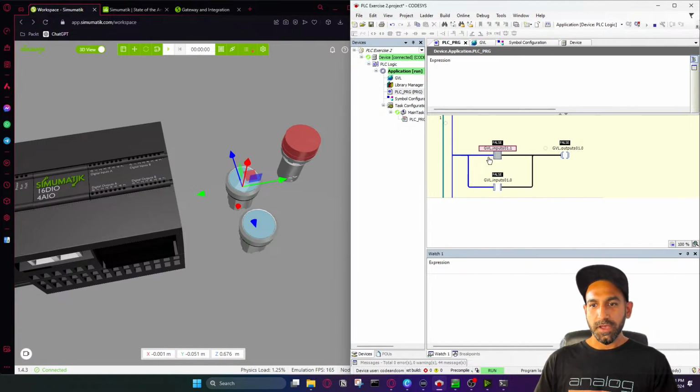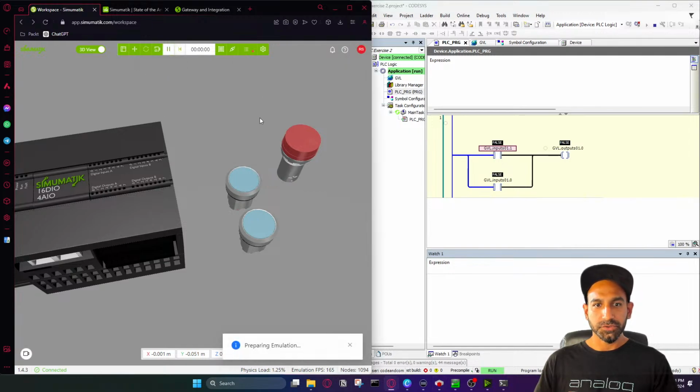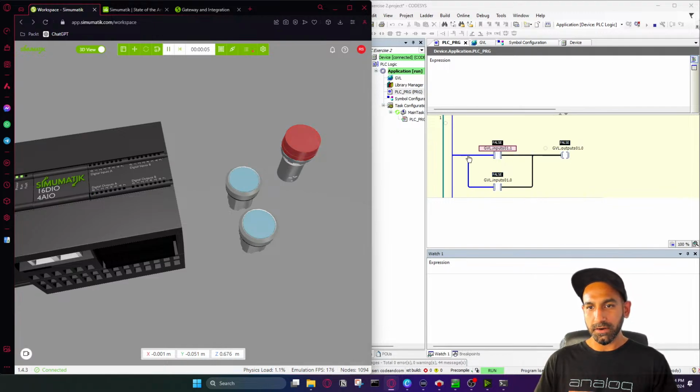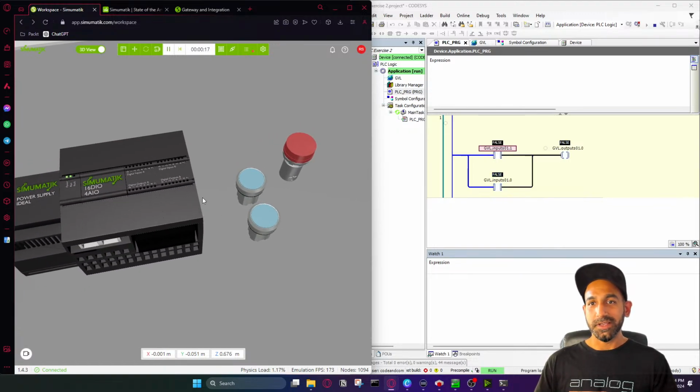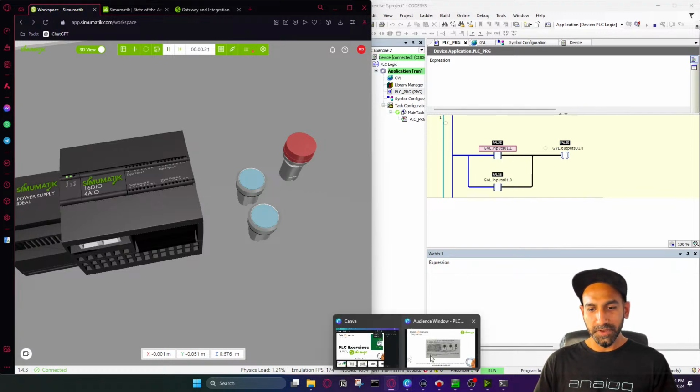So right now you have two inputs. So if you press any of the inputs, the output should be true. So in this case, you can see that output is true, and this is actuating the parallel ladder. Okay, and this one is actuating this one. So with both inputs, the output is true. Super easy to realize, and along with the wiring, I think it's super fun to do. All right, moving on.